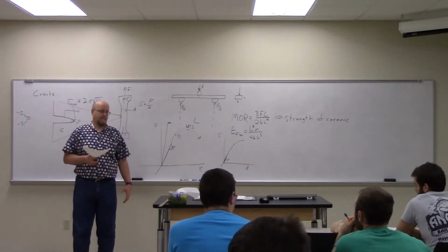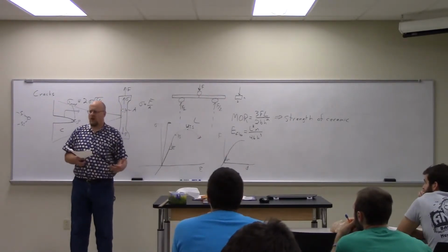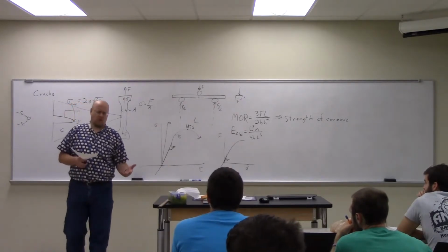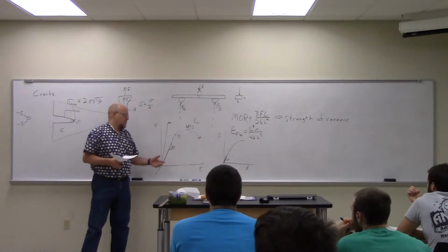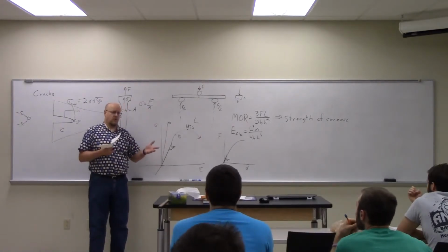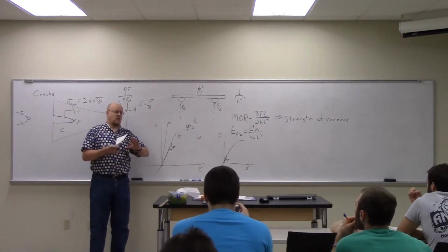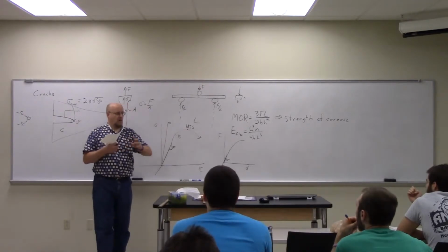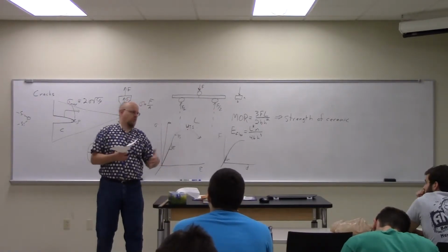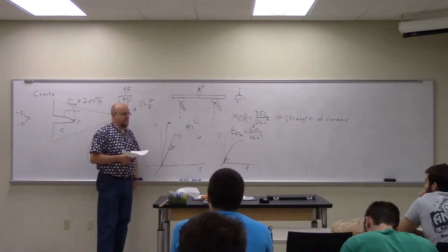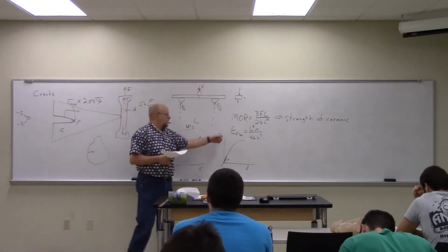Okay? And again, that relates to, I think we'll talk about that at some point when we talk about polymers in greater detail. But that's because when you pull on a polymer, you're actually aligning molecules. Right? You're changing the molecular, the atomic alignment when you pull on it. Whereas when you push on it, you're not really changing. So E flex is for polymers. This is primarily used for polymers.